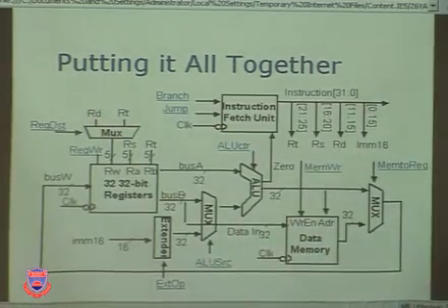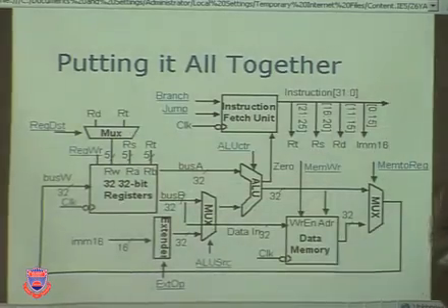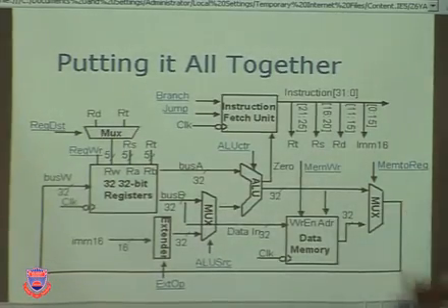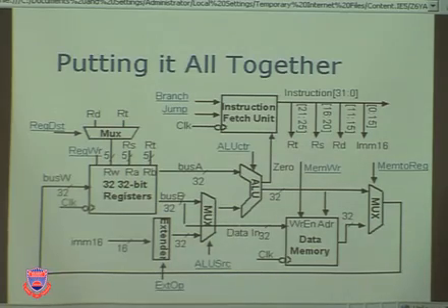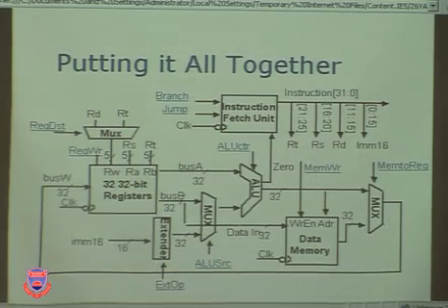That means they're sequential. And what does that mean about this box, this box, this box, this box, and this box? What does it mean about those? They're combinational. They have no clock. They're simple combinational circuitry. Inputs now determine outputs right now, or a little bit later if you add realistic gate delay. Okay? Remember all those lessons from CS-224? I'm just reminding us of what kind of hardware we have up here. A mix of sequential and combinational.